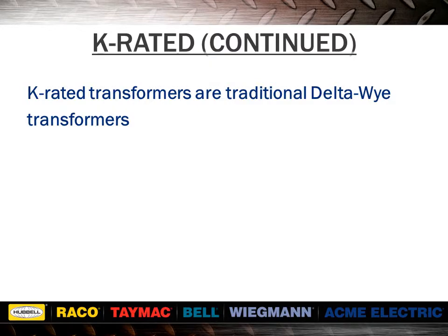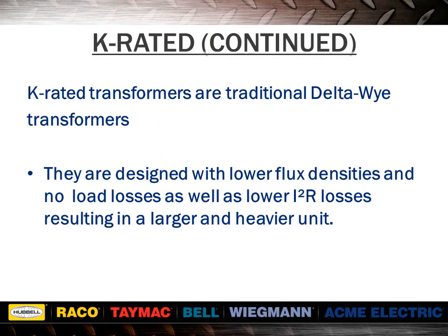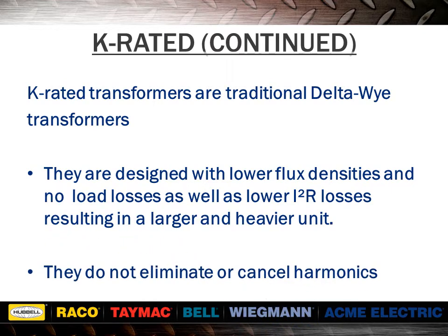K-rated transformers are traditional delta-Y transformers. They are designed with lower flux densities and no load losses, as well as lower I²R losses, resulting in a larger and heavier unit. They do not eliminate or cancel harmonics.